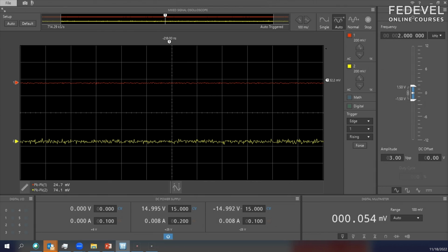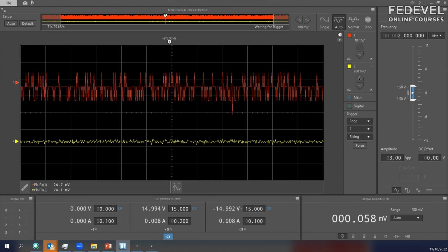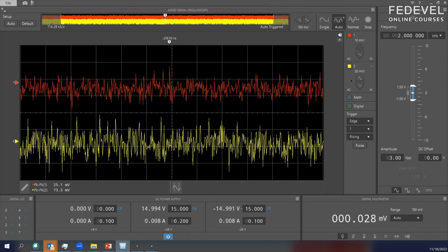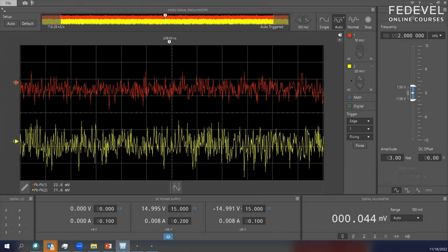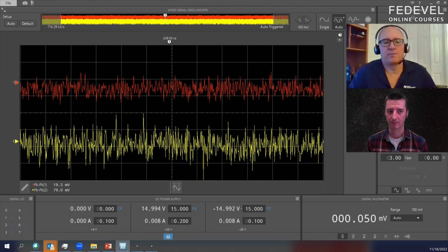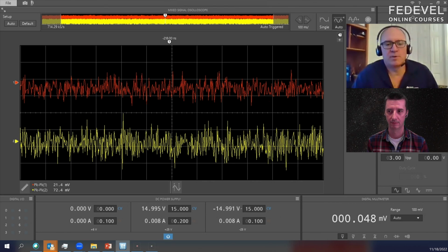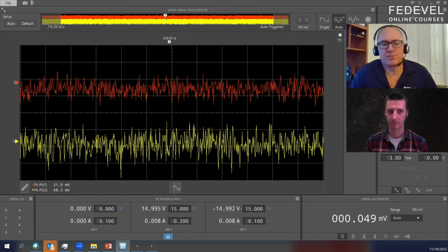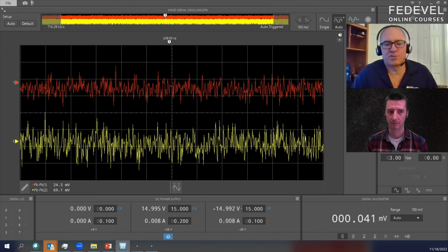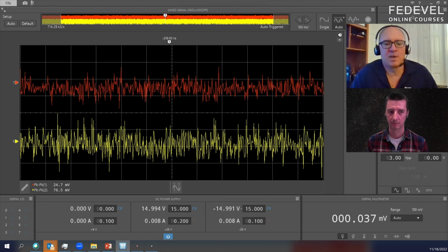But we can also look at intrinsic noise. The walkie-talkie is generating extrinsic noise. So what is the difference? Extrinsic means it's coming from outside and causing the disturbance. The intrinsic is noise generated by the parts themselves. Resistors, for example, generate intrinsic noise. The random motion of electrons within the resistor will generate noise. The larger the resistor, the more the noise, and the higher the temperature, the noise will also increase.